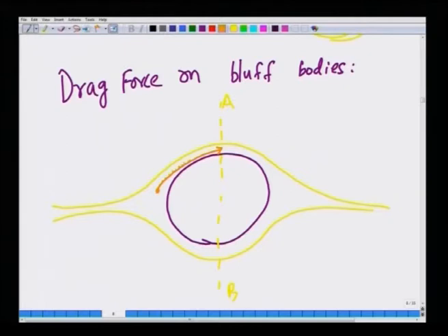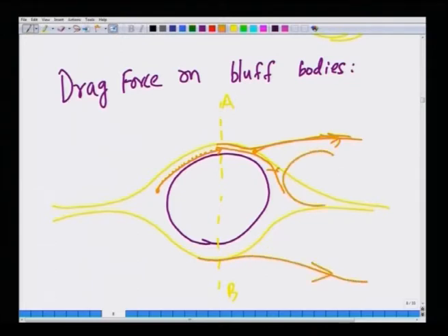The pressure is decreasing as it goes, but when it goes from here to here, it is facing an adverse pressure gradient. So, the particle comes to a standstill at some point because of the viscous effects close to the boundary layer, and it gets washed away. The actual flow profile will look like this, and this region of increased circulation is called the wake.